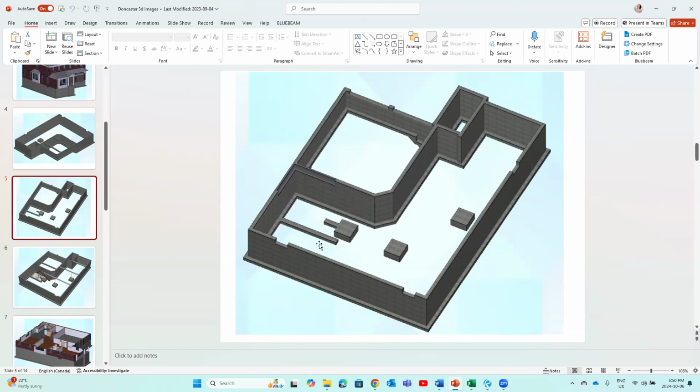That's why we're going to take the perimeter of the basement foundation wall, plus the length of this wall here, cold cellar, plus the length of this wall. I should say plus the length of this footing and the length of this footing, since we are looking at the formwork for footing. Get that, multiply by 2, and we get both sides. Okay, so we need to think about what we need to do for a step footing like this.